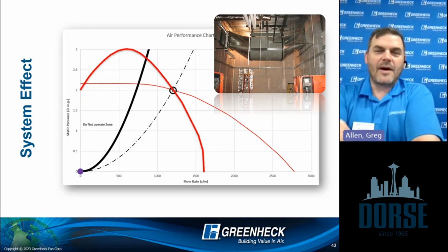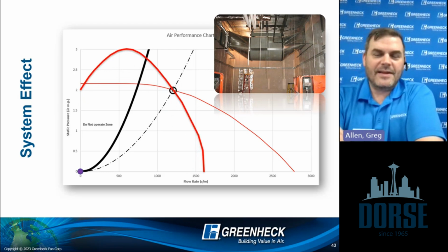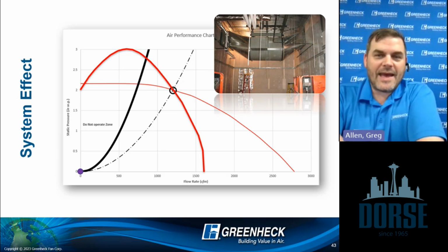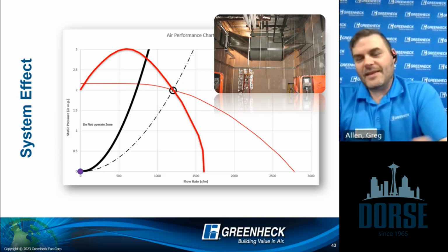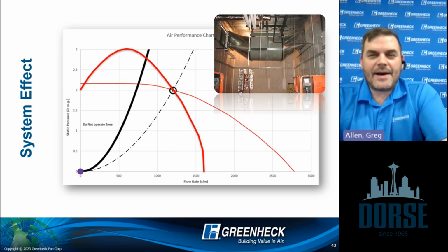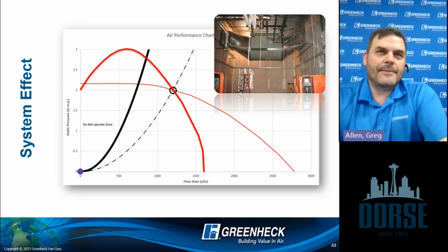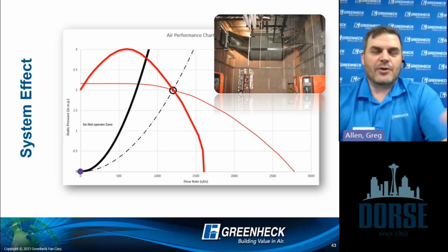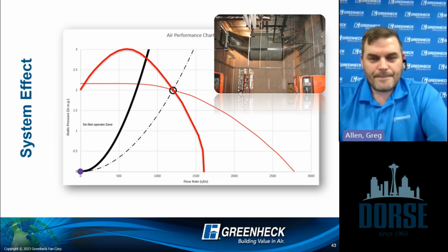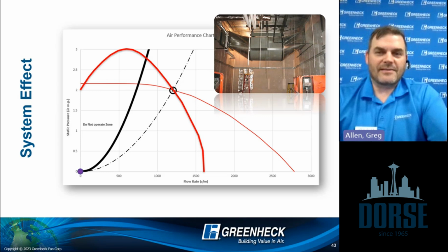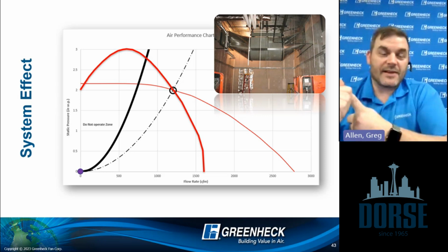Now, remember, fan curves offset parallel. If I speed that fan curve up, it maintains its shape, but I had to speed it up quite a bit. So in this scenario, I have a not opportune installation, right? I've created a scenario where the fan is less efficient at even moving air. And now to get to the right volume of air, I had to speed it up. So now it's going to be louder because I sped it up.